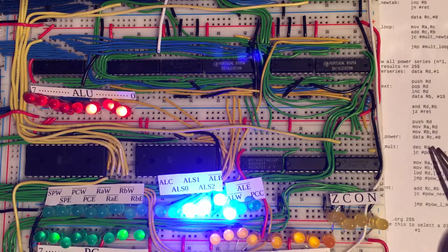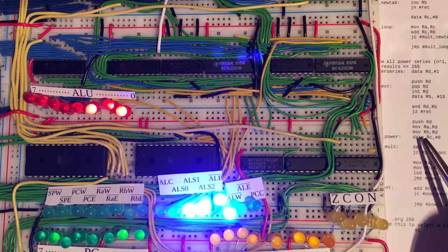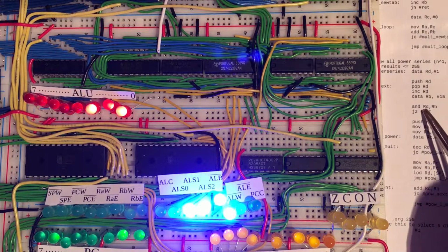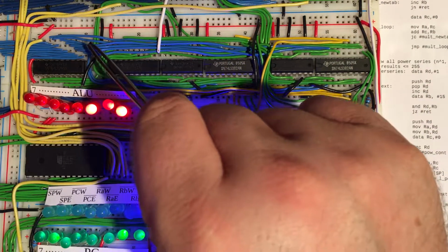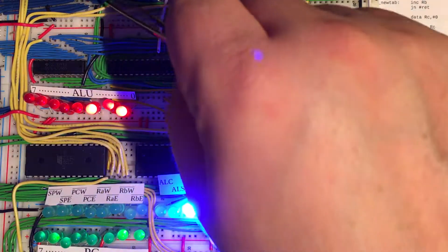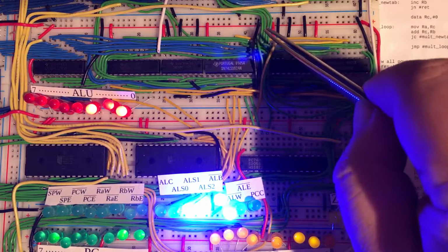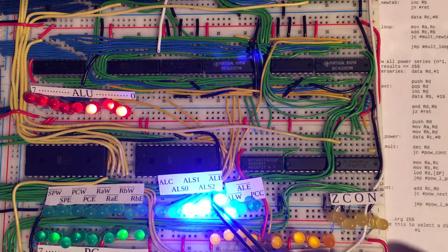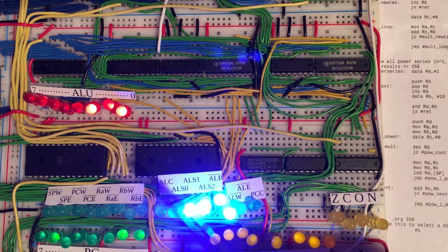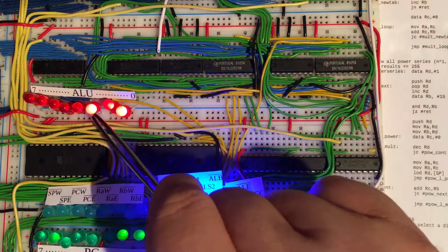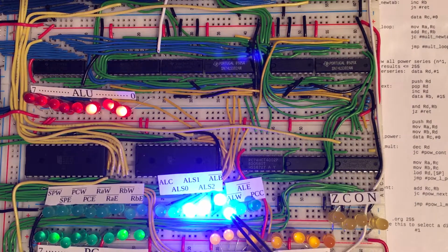But of course the other operand is the D register, and that's coming in through the bus. And so that contains a value of 7 right now, and on these B wires we are having a value of 15, and so the ALU is then going to perform this AND operation on those 2 bits, and so the result once again will be latched into this register, because we're telling that register that we would like the output of the ALU to be written.